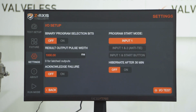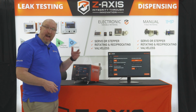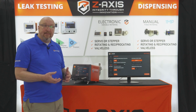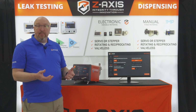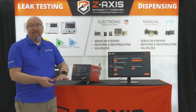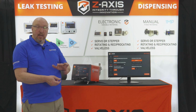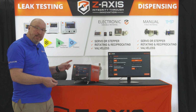The I/O settings. If your tester is equipped with a remote I/O for a PLC interface, this is the screen where you would come off and select whether you want the I/O to be able to select programs or how you're going to start it. We have some built-in start modes that are helpful if there's some automation or semi-automated processes. One of them is the ability to do a fixture lid close, where the part has to be loaded and a lid closes for safety, in case like a blast chamber. The lid closes and the test won't start until the lid closed is sensed. An input on the I/O needs to be sensed. If the lid opens, the test won't be able to start.